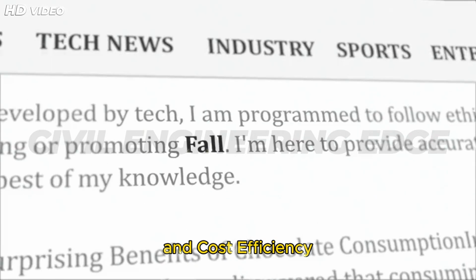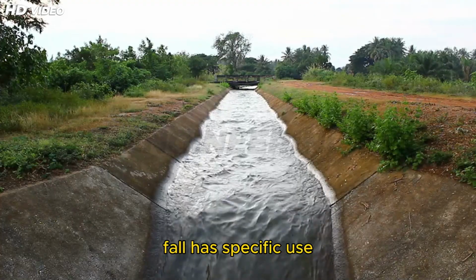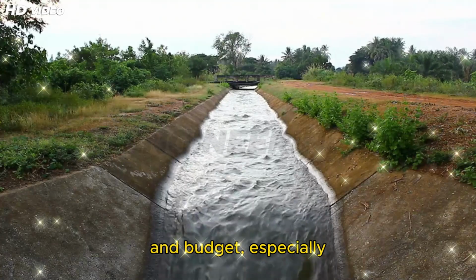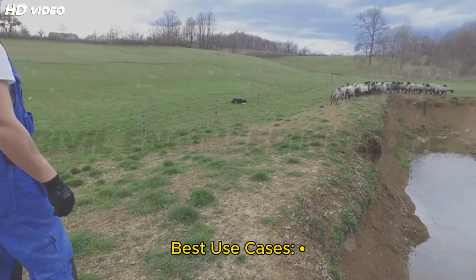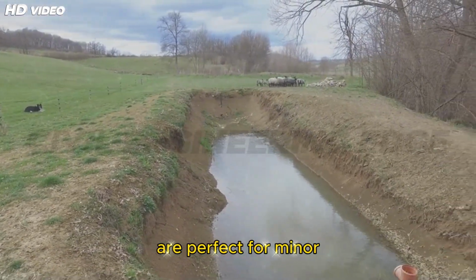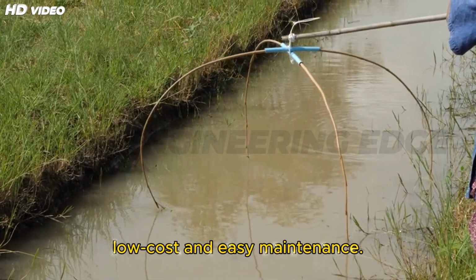Segment 10. Best fall uses, benefits, and cost efficiency for India. Each type of canal fall has specific use cases depending on terrain, discharge, and budget, especially in a diverse country like India. Best use cases: vertical drop and trapezoidal notch falls are perfect for minor canals in plains, offering low cost and easy maintenance.